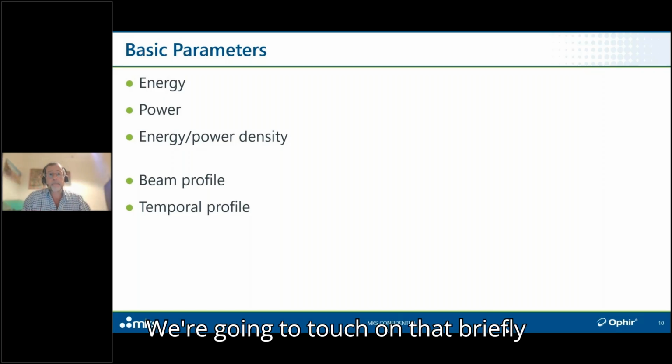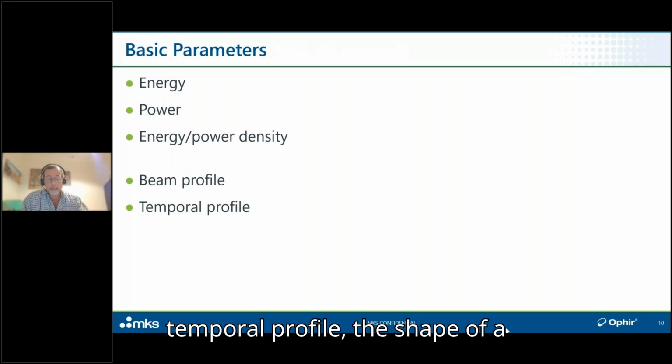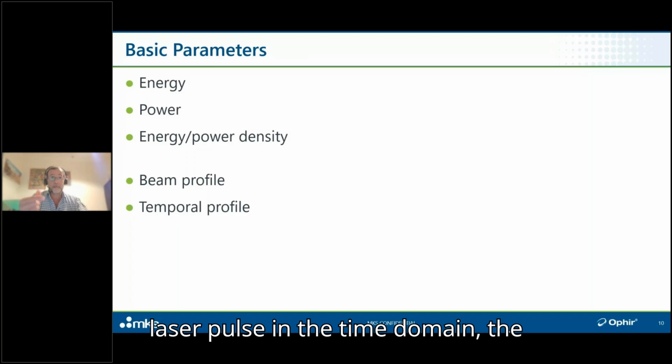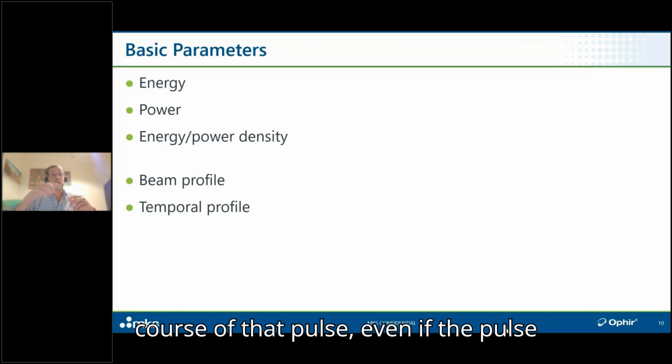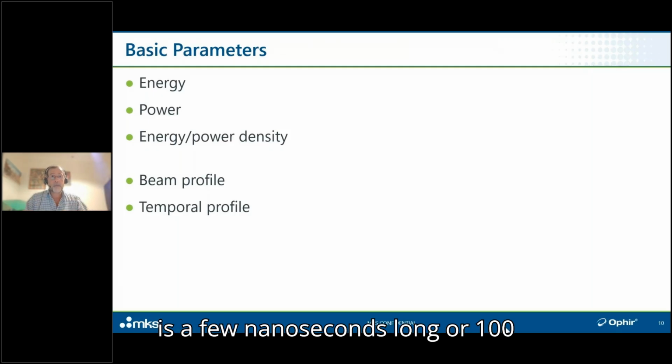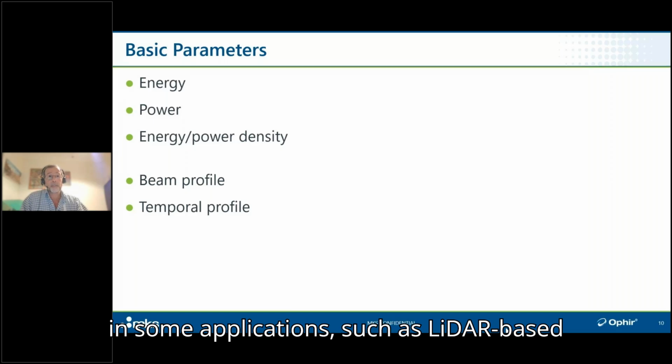That can be important in some applications, such as LiDAR-based distance measurement, which we mentioned a moment ago, since with LiDAR, we're basically measuring the time of flight of the pulse in order to determine the distance. So the time, shape, and width or duration of that pulse obviously is going to affect the distance resolution with which I can measure.